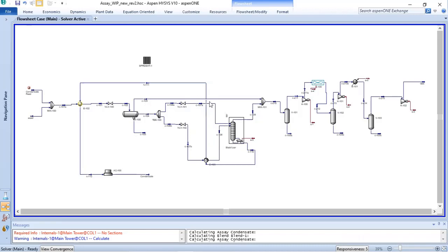Once we have the gas, it goes to the compressor suction, and we have a recovery of this liquid, and so we have a split of this liquid and a preheating of it before entering the absorber, and a source of heat to add heat to this in order that the liquid can vaporize and goes to the compressor suction.